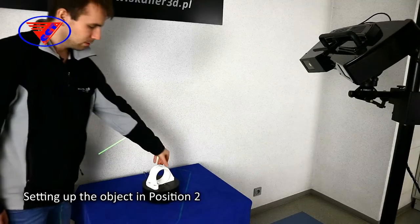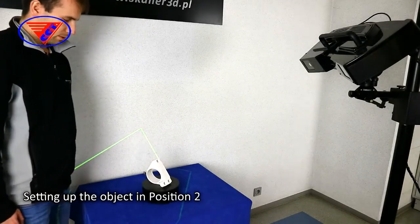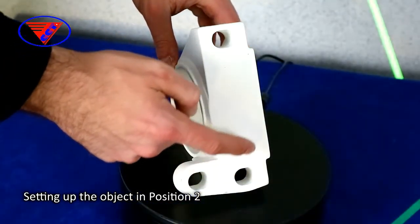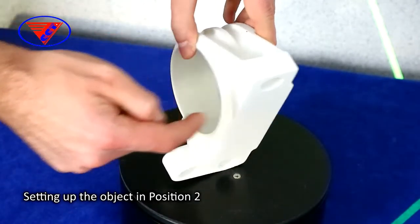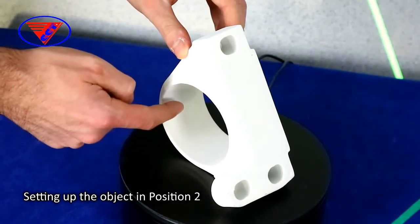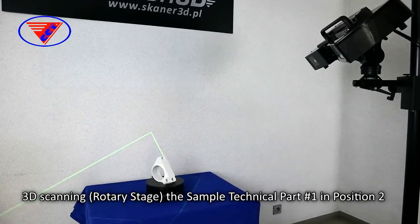For scanning the bottom surface, change the position of the object on the rotary stage. In this position, the most important is to scan the bottom surface and the edge of the bottom surface and perpendicular surface showed on the screen. Also, it is important to scan the cylindrical surface. We will scan the object in this position with the step of 30 degrees around.